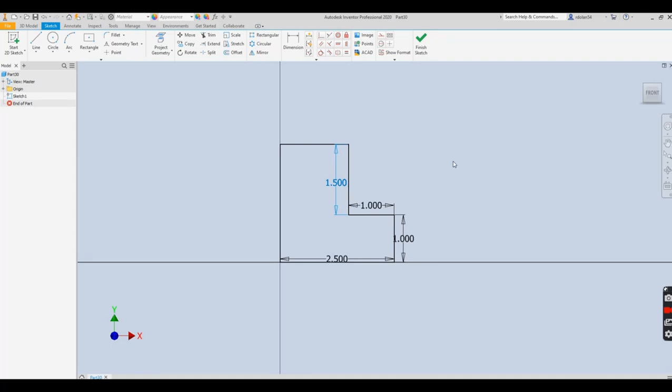Okay, first I'm going to take a look at moving it. If we go to move, which is up here, I pick on move again. It asks me first to select what I want to pick. So I'll pick these guys here. Now it wants a base point. The base point can be here, for example, that end point. I could go here and try to find the midpoint of one of these lines, which I can't, or I could just pick a spot anywhere.